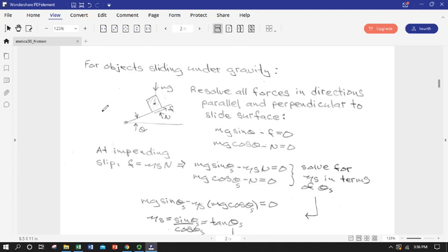And what it means is basically the maximum angle at which you could tilt something before it would begin to slide down a surface. So if you're worried about some big block of rock sliding down maybe a geological contact towards something parked in your parking lot, that becomes very important. It's actually a consideration in highway design in steep terrain. So we can define that just by drawing an FBD of a little block on a theoretical slope.